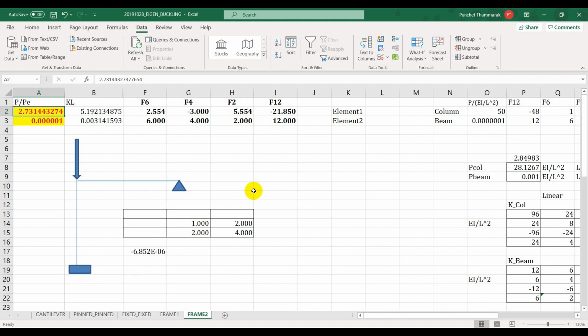But that estimation was not precise because you initially assumed the value of P. Okay, so the stiffness was not correct at the first analysis, but then you get some value. You will update your analysis using the calculated P distribution in each column for the second round.